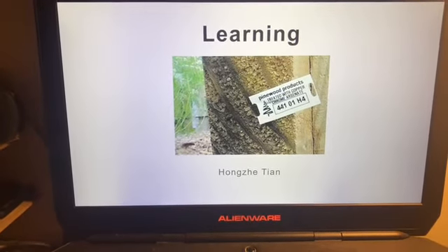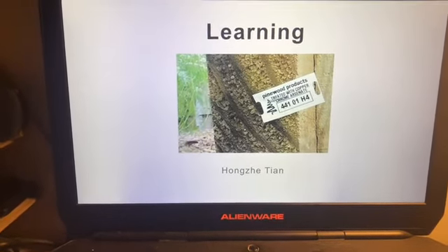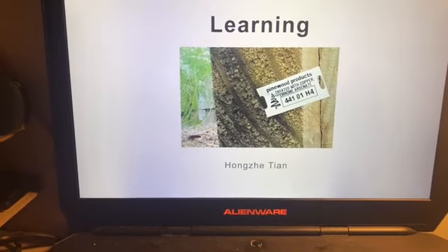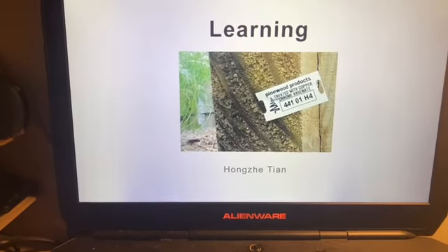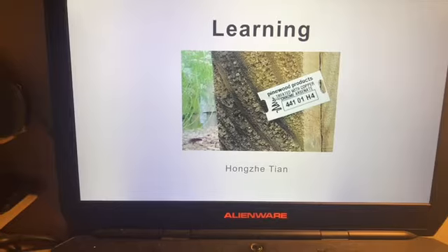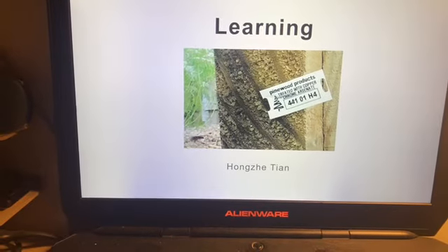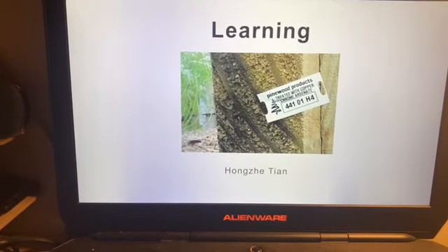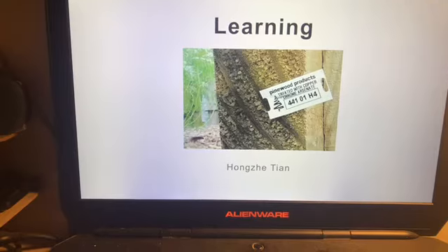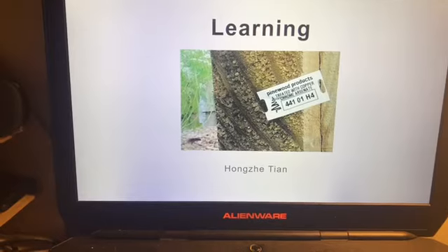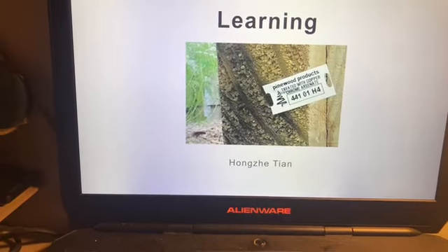Through the unconfined compression test program, the research evaluated the effects of material content, porosity, molding moisture content, and water cement ratio. The experiment is divided into three parts. Firstly, the characteristics of soils are described. Next, the amounts of lime and cement are measured, and then a series of unconfined compression tests were carried out. Finally, a series of conclusions are drawn.